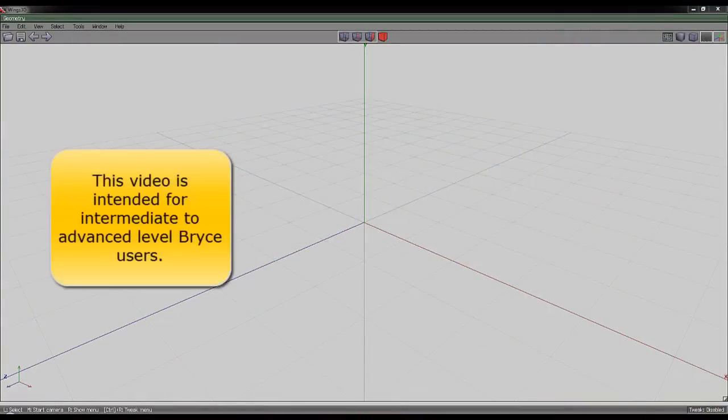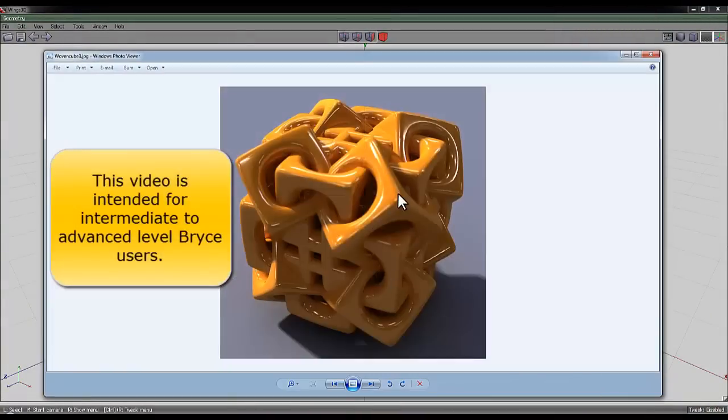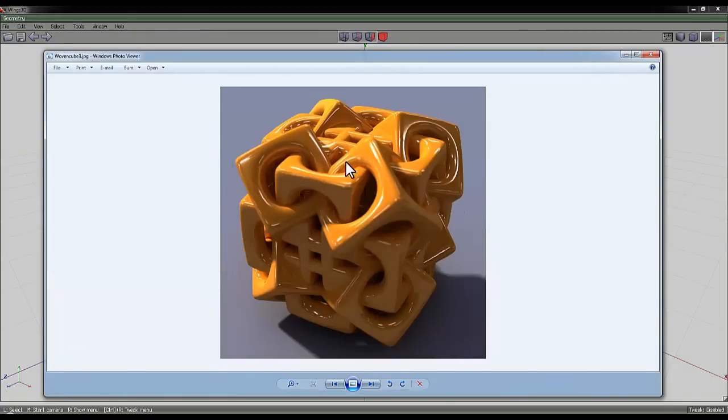Returning then to the topic of modelling things like that in Wings 3D, when I made that I was thinking, would it be nice if I could get these corner cubes a different colour to these middle face cubes? But because I'd modelled it all in one object, it's very difficult to separate out the materials after that so that Bryce can render them in a different material. So what I need to do is create two objects in Wings that have this same interlocking relationship, so we'll have a look at that.